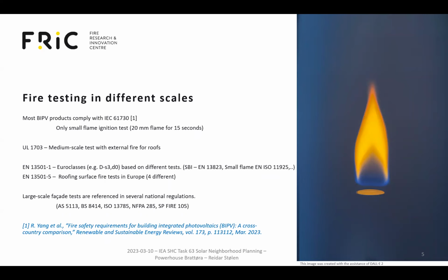One of these tests is the ignition test. It's basically a small match-sized flame that should be held against the PV module for 15 seconds, and it should not catch fire from that.